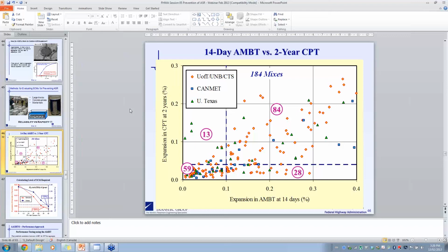One of the techniques we found very useful to determine if DEF has been and is still an issue is if you take small cores of the concrete, soak them in water. With small cores soaked in water, further ASR is unlikely because the alkalis will leach out very quickly, but it is a way of stimulating DEF, and we've actually done that in the laboratory and written a paper on that. I'd be happy to share with the person who asked that question if we get his question in the form of an email.